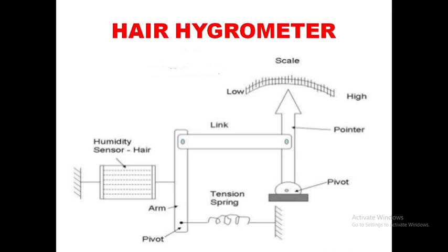Basic principle of hygrometer: due to humidity, several materials experience a change in physical, chemical and electrical properties. This property is used in transducers that are designed and calibrated to read RH directly. RH is nothing but relative humidity. Hygrometer is a type of absorption hygrometer and uses the mechanical humidity sensing technique.